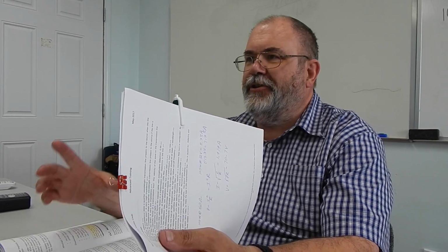The cross section of the waveguide, the diameter if it's round, the long section if it's oval, or in the case of rectangular waveguide, the wide part of the waveguide, has to be at least a half wavelength at the frequency we're interested in. You can do the math at 1500 megahertz. Any frequency below that half wavelength is cut off, which effectively makes waveguide a high pass filter. It'll pass frequencies above that cross section half wave, but anything below is cut off.